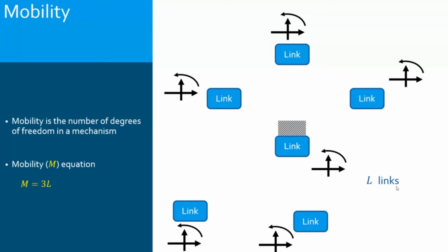So first, it is the ground. The ground is the first consumer. The ground will already take how many? The 3. Why? The ground is considered non-moving. It's the reference. I will study the motion of this link, this link, this link, this link, and the other one relatively to the ground, to this one. So for me, this one is not moving. When I consider the motion relatively to a reference, I'm considering that reference is fixed, is not moving, is static.